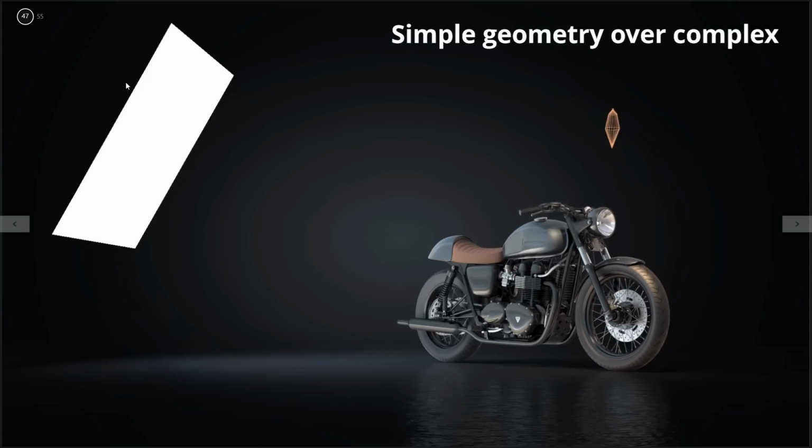Another tip that I can give you for working with physical lights in your scenes: use simple geometry whenever you can. Instead of bringing in a cube and making it a light, use a plane. A cube has 6 sides, so light's shooting out in 6 directions. Additionally, every surface of that cube actually has an inside and an outside. So even with a cube, you could be looking at light having to be calculated from 12 different directions. Instead of working with solid bodies, work with things like planes.